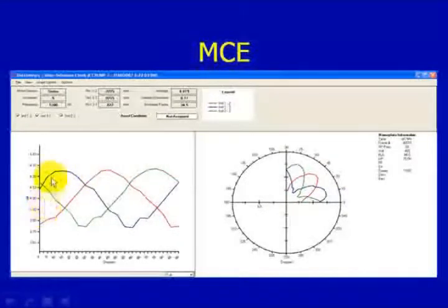What we're doing is we're taking the rotor, we're applying a high frequency 1200 Hz signal to the stator, developing a field on the stator, and we have the residual field on the rotor. And as we rotate the rotor through this field, and depending on the number of poles, it would either be in 5-degree or 10-degree increments, or less than that if it's a higher number of poles. What we then do is we measure our inductance over that period.